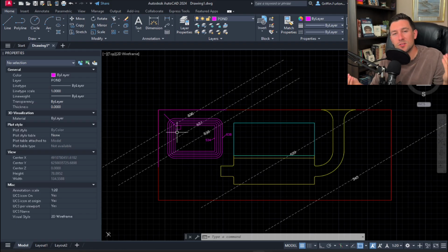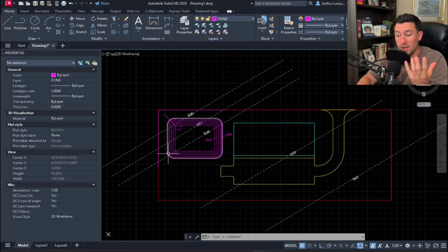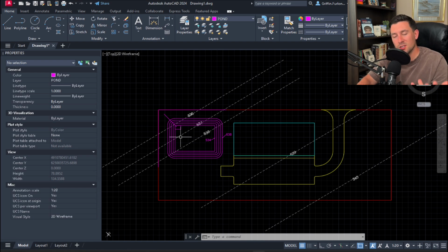And this is the golden thing of what I've been trying to get to this whole time leading up to this video: sometimes stormwater design is an iteration game. Sometimes you will have to play with the volume, sometimes you will have to play with the weir configuration, the size of the weir. This is actually when it becomes fun. The first step is just getting to this level of actually having some sort of design to work with.